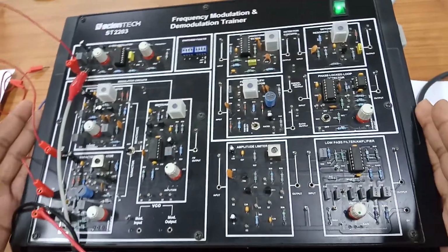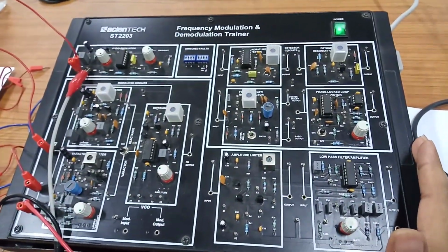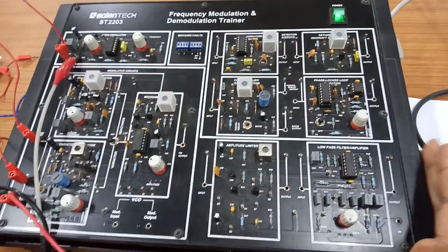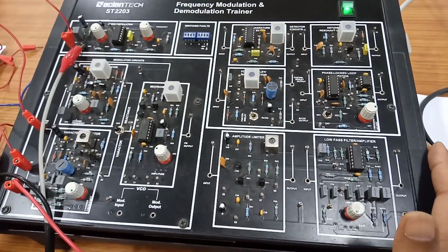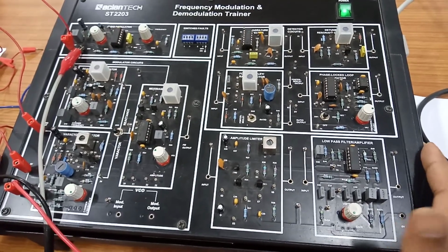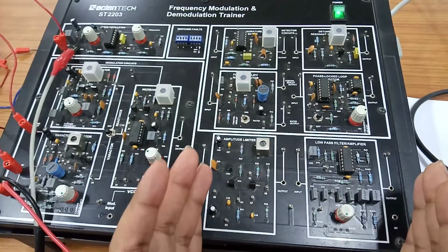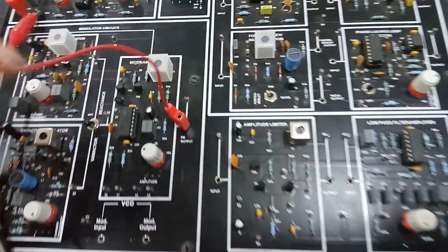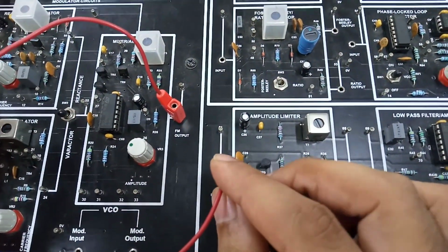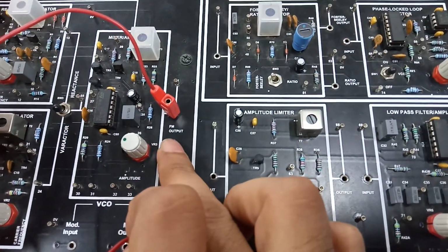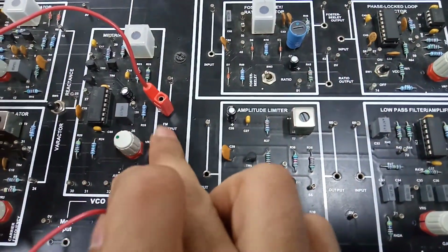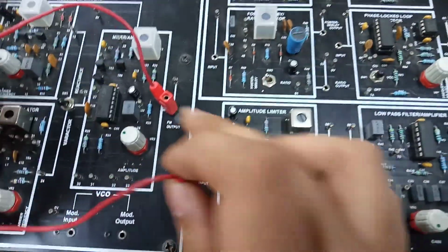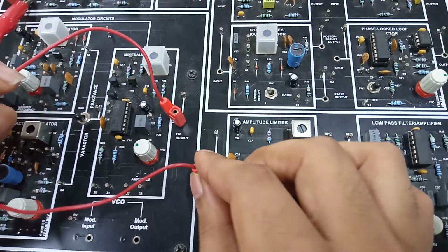So this kit is a prototype in order to see how frequency modulation and demodulation take place and how the waves look. We are verifying this, and our objective is to see what frequency modulation and frequency demodulation are and how they are done. So we have both transmitter and receiver in the same part. We are going to assume that whatever we transmit at the transmitter part, we receive the same at the receiver part. So I am connecting this FM output, that is the signal we need to transmit through an antenna. Here we are using it on the same kit. So I am connecting this output to the input of the amplitude limiter.